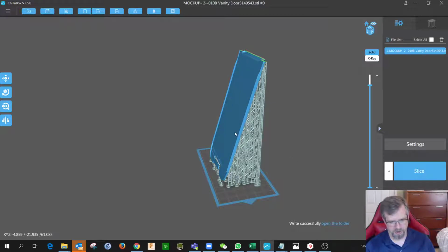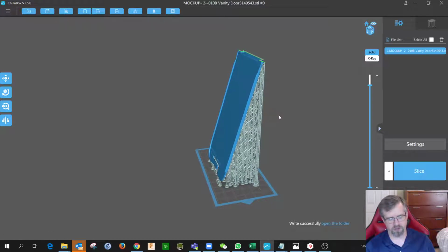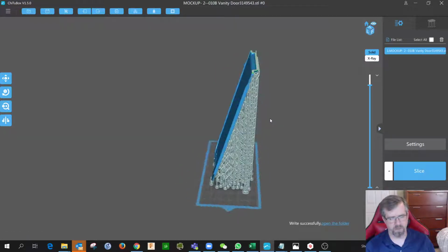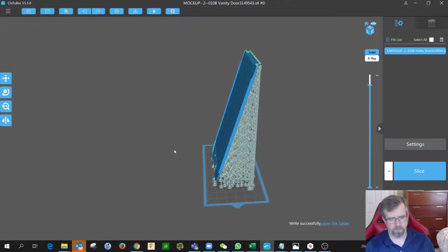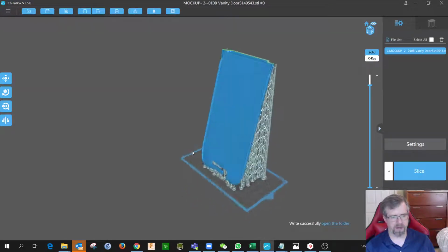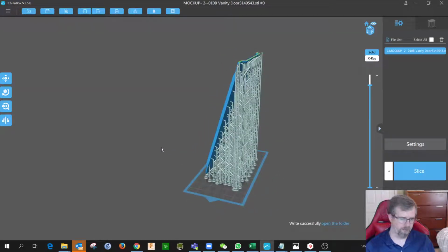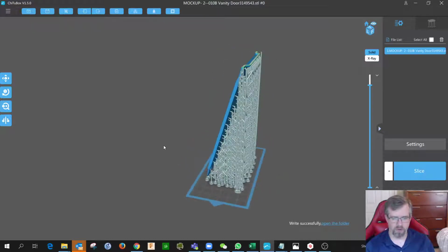If you don't do that, you can open up your kind of slice file that we just saved before this and put it in here, but what will be different is the supports will not be editable. It will treat that object along with all of the supports as one solid piece of 3D data. So I don't recommend using that as your go-to method, but in a pinch, if you have to, you can go into that model and add supports, but you really can't take them off. Okay, our project is saved, our slice file is saved.